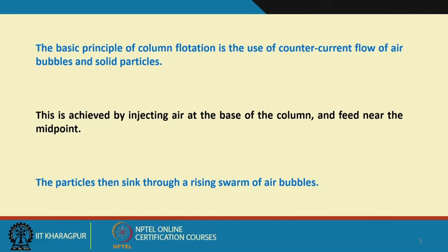It is a very complex hydrodynamic situation, and the basic aim is proper mixing for bubble and particle attachment, creating a situation where every particle has a chance to decide whether it will adhere to the surfaces of the bubbles or not. That is dictated by the nature of those particle surfaces, that is whether they are hydrophobic or hydrophilic.